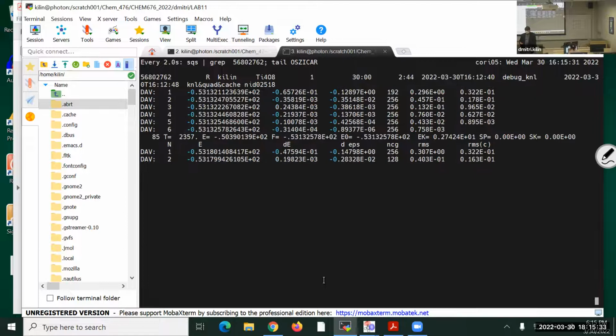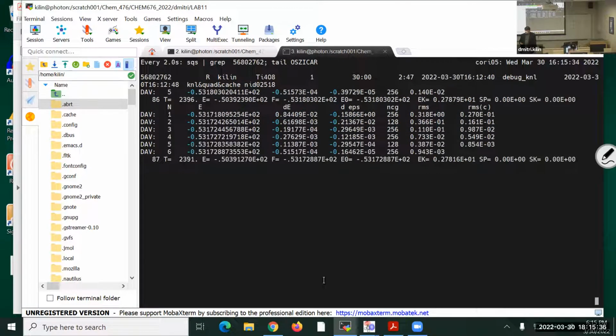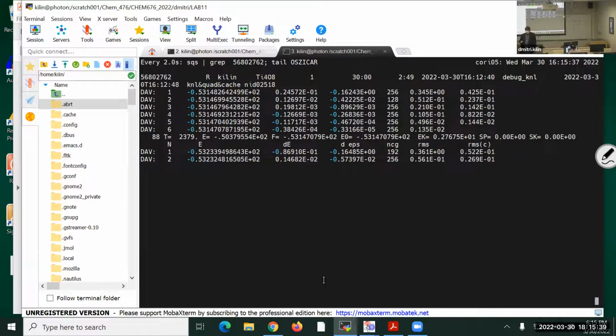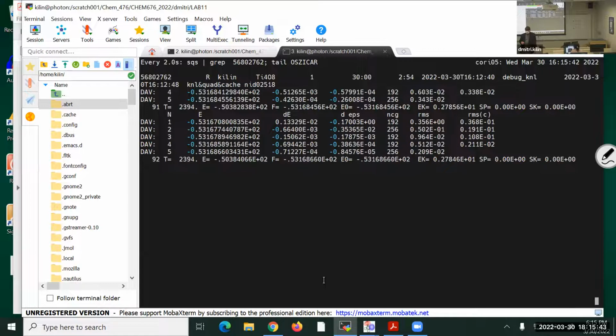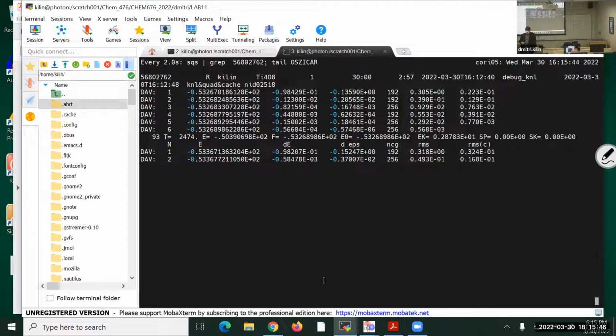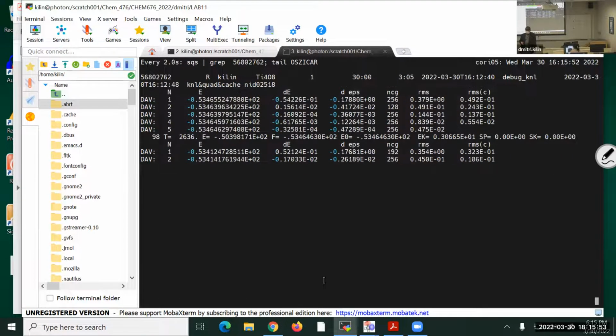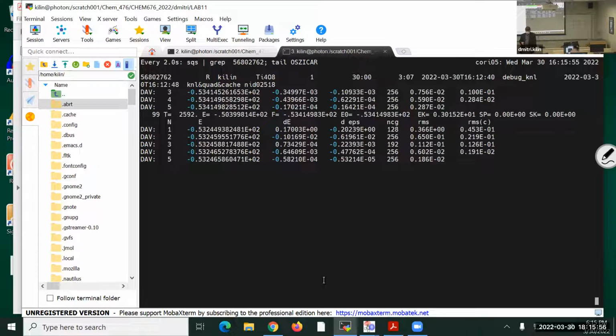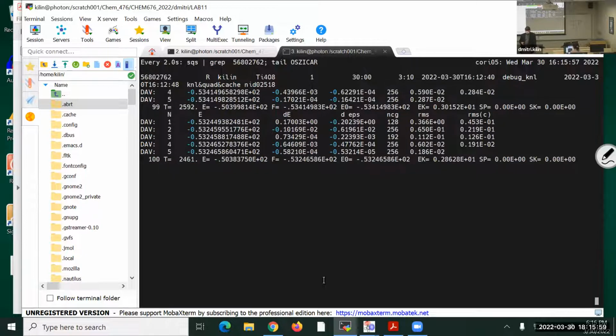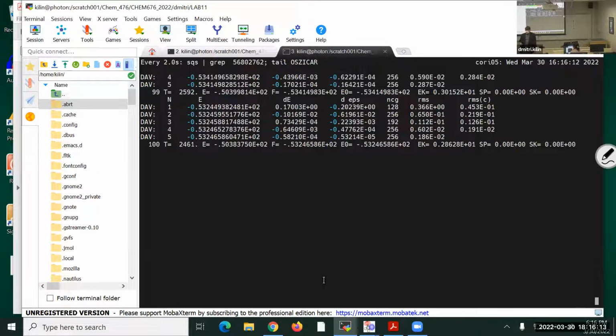In order to be a little bit more universal, we may convert this large OUTCAR file into a file that contains only XYZ coordinates at each time step. And there is a standard toolbox which is created not by VASP designers but computational chemistry enthusiasts. And this toolbox for processing VASP output is available both on Photon and on NERSC. So in this toolbox, there is a utility, there is a procedure that converts OUTCAR into XYZ format. And this XYZ will be more universal. You can open it with basically any computational chemistry software. So I will just demonstrate this little piece of software.